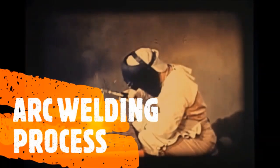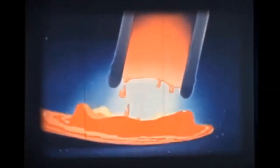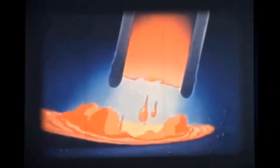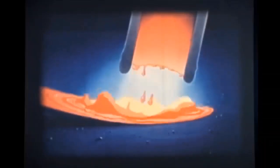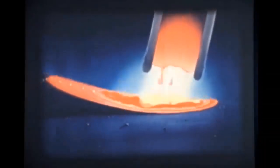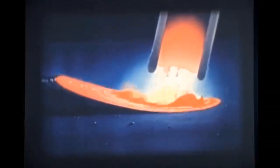When the arc is struck, it almost instantly creates a temperature of about 6,500 degrees Fahrenheit. This melts both the base metal and the metal in the electrode. The metal from the electrode is melted off in tiny droplets, is carried across the arc and mixed with the molten base metal. The force of the arc and the forward travel of the electrode causes the mixed molten metal to be pushed to the rear of the crater, where it cools to form a bead.